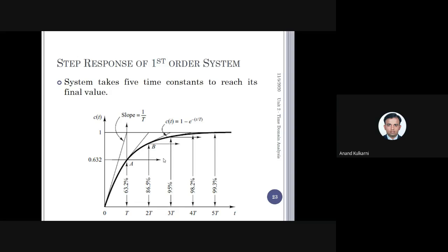Why this is important is that depending on this analysis, you decide which device is used for measurement. Now, in our metrology lab or measurement lab, you have done temperature measurement using a thermocouple and a thermometer, correct? You might have noticed you have to wait a longer duration for the temperature to stabilize in a thermometer, whereas the thermocouple gives the reading more or less instantaneously.